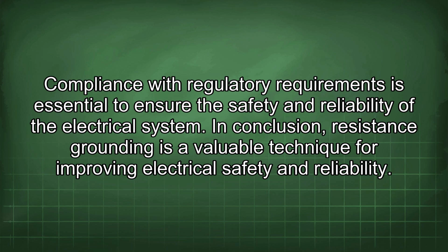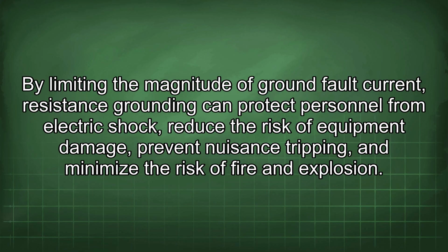In conclusion, resistance grounding is a valuable technique for improving electrical safety and reliability. By limiting the magnitude of ground fault current, resistance grounding can protect personnel from electric shock, reduce the risk of equipment damage, prevent nuisance tripping, and minimize the risk of fire and explosion.